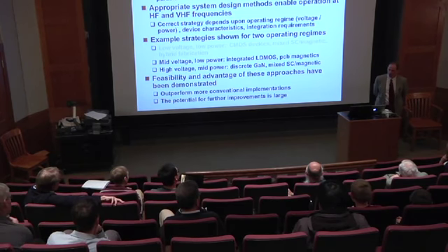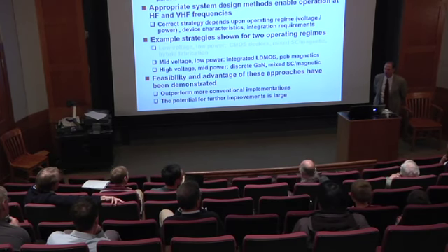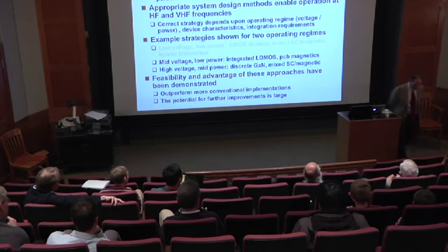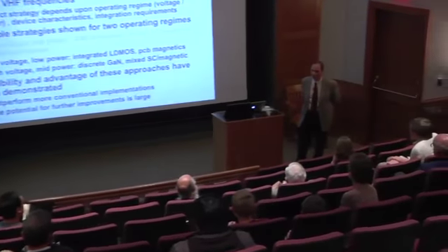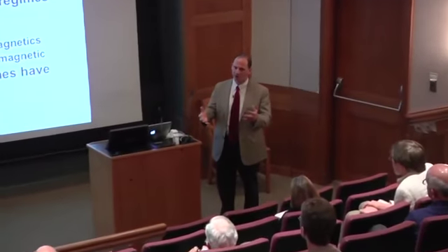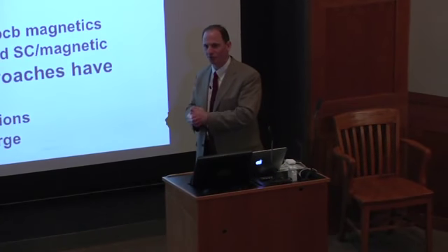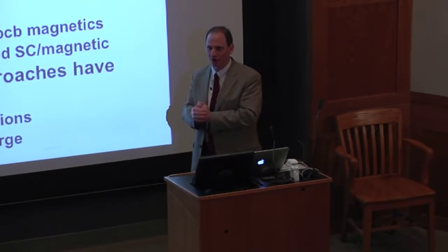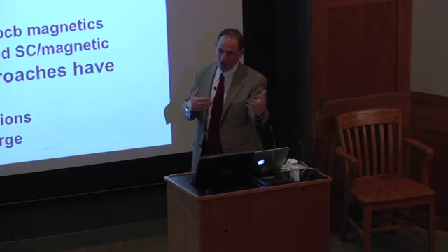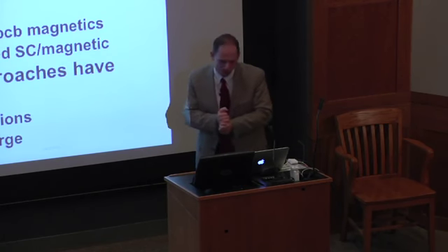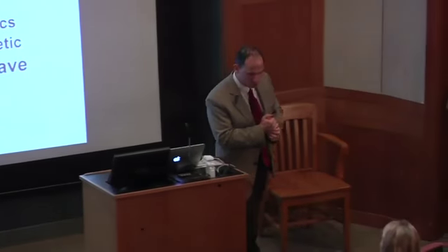If you're at industrial power scales and you draw a poor power factor, you get charged for that. And in Europe, particularly, standards are emerging for the higher power devices. And even in the United States, to get 80+ certifications or Energy Star certifications on your devices, people are starting to look at either THD or power factor as a constraint.